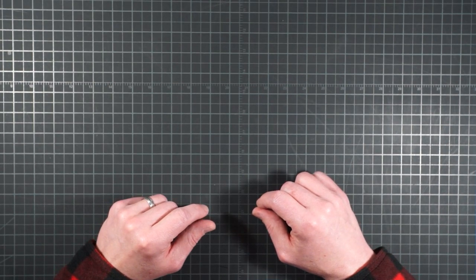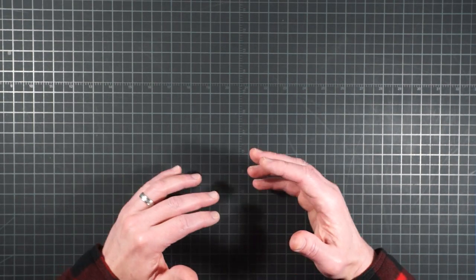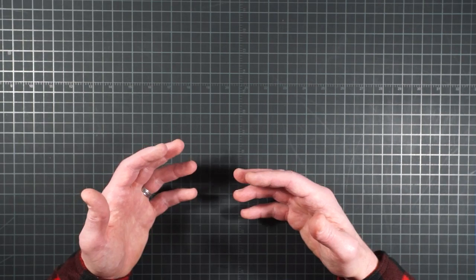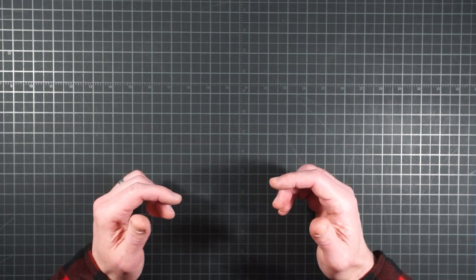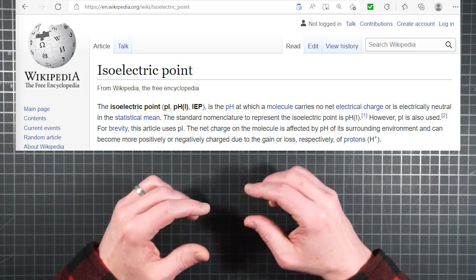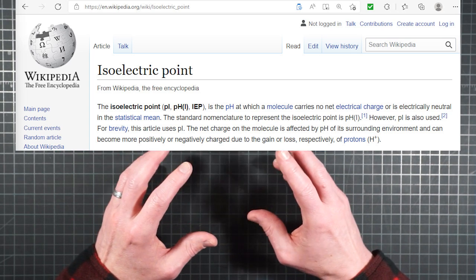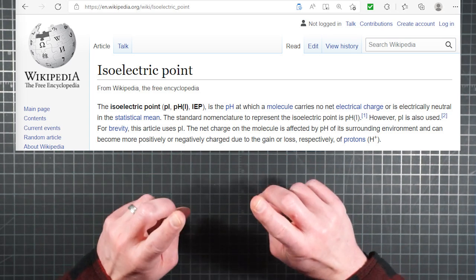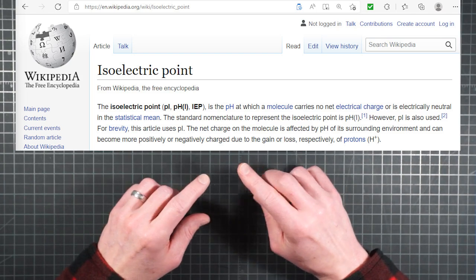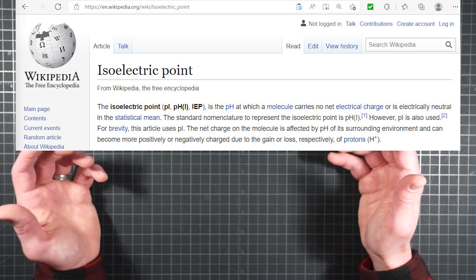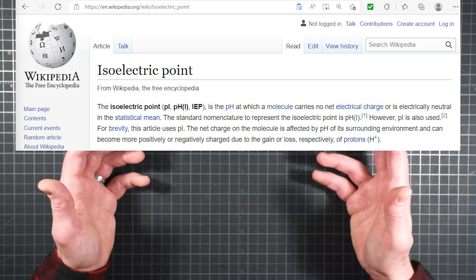So there's another potential issue with a technology that uses electrochemical attraction, and that is the electrical charge of the particle in question. And viruses can vary significantly in their charge characteristics, and that net charge can vary with pH. So if you're relying solely on adsorption for virus removal, you might want to know how the filter performs against viruses with different isoelectric points.